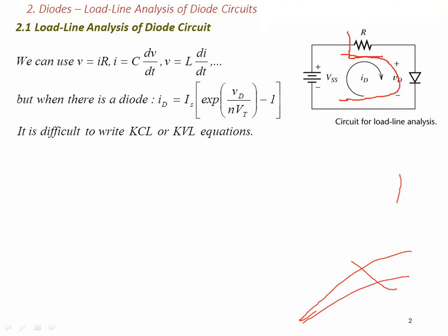The resistor is a current limiting resistor so that we don't have an infinite current or a current that is too big. So R is just for current limiting purposes. In this connection, since the anode is connected to the positive side and the cathode is connected to the negative side, this is already forward biased.